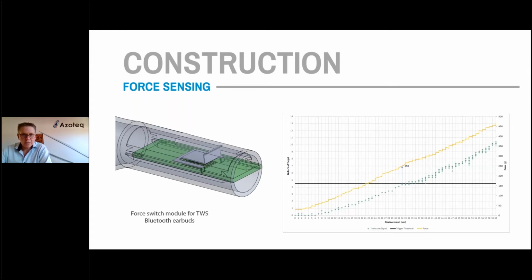So from 0 micron all the way up to 60 micron, we get a very linear response from the inductive sensor. So this is a technique, a tool, sensing IC to measure very small deflections at a significantly lower power consumption than you would have needed otherwise for a technology like a strain gauge or such.